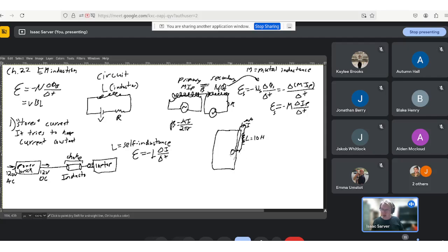Well, someone comes along and opens the door, opening the circuit. Now the circuit wants to go, instead of going through the door latch, through the person. But this massive inductor is saying the current shall remain. And so the person who has opened this door becomes part of the circuit and is now receiving milliamps of current.